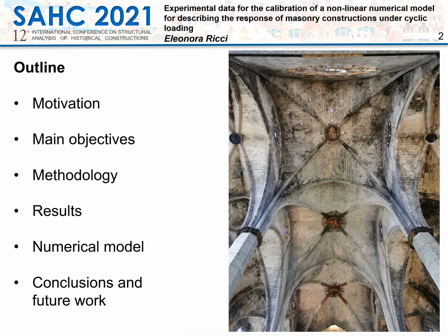Starting from the motivation and the main objectives of the work, I'm going to describe the experimental investigation that we carried out, and after discussing the results, I'm going to present the numerical model that we developed in a finite element software called Abaqus in order to reproduce the seismic response of the analyzed structure under cyclic loading.